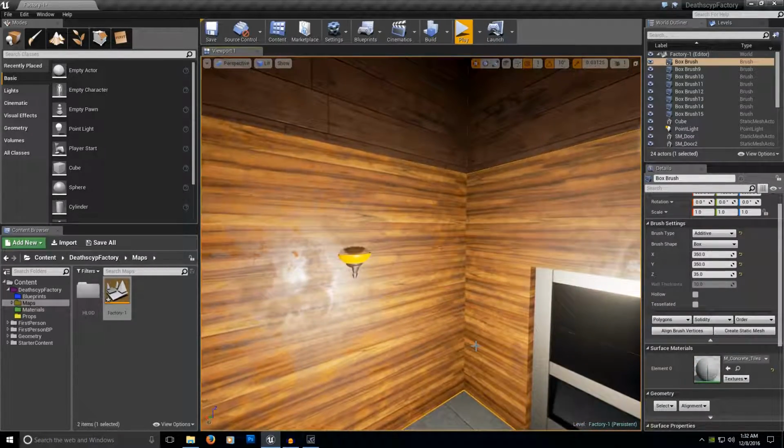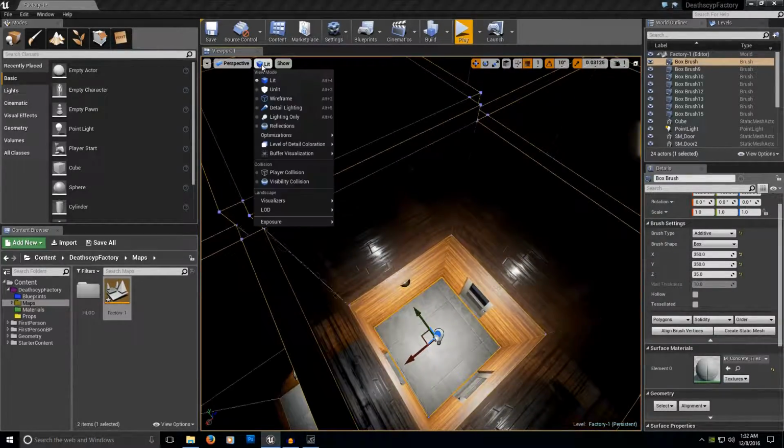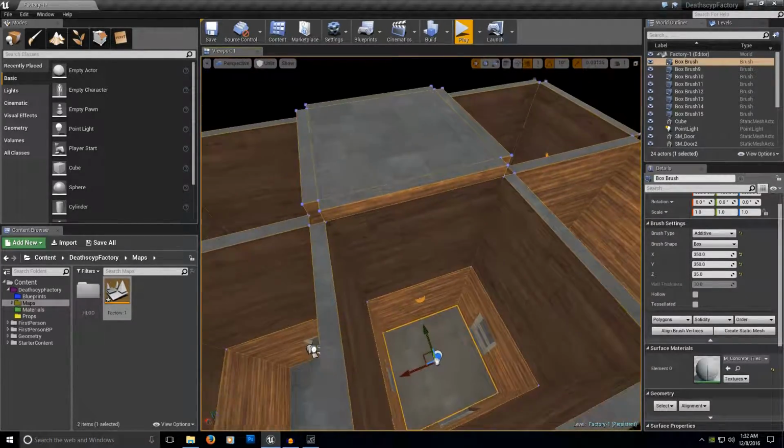To make my scene look a little bit more realistic, I'm going to use the post-process volume, as I like to have the real measures when I put my light. I don't like the auto eye adaptation feature that the Unreal Engine gives us. It's not a bad feature, it's just that for this tutorial I don't find it useful, because the light is always going to play around, and sometimes it takes a long time for the eyes to adapt. You're going to understand what I mean by that. The camera has an eye feature. So right away, go back to unlit mode.